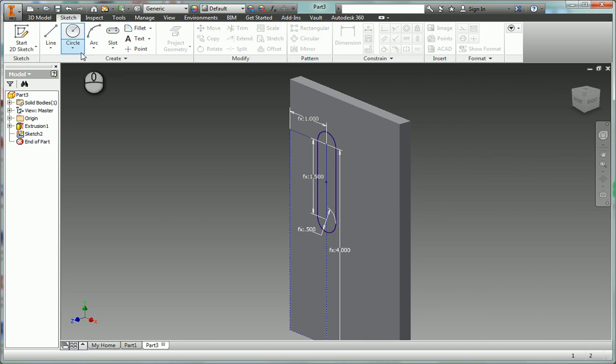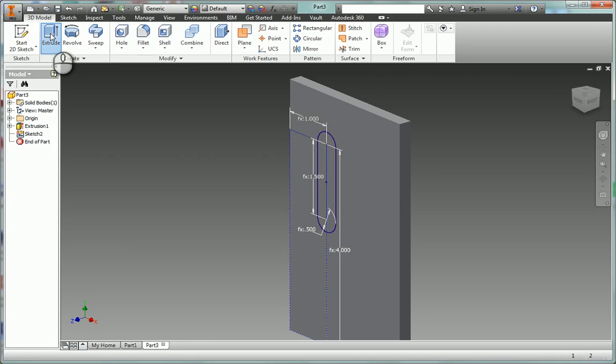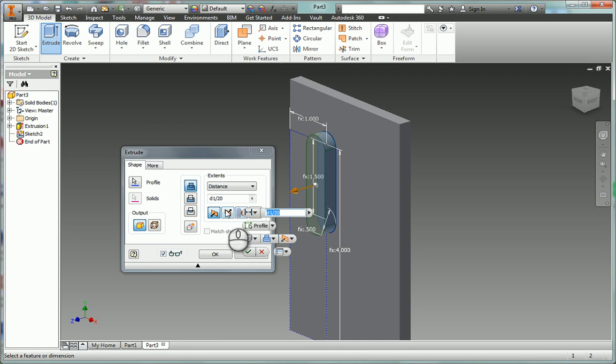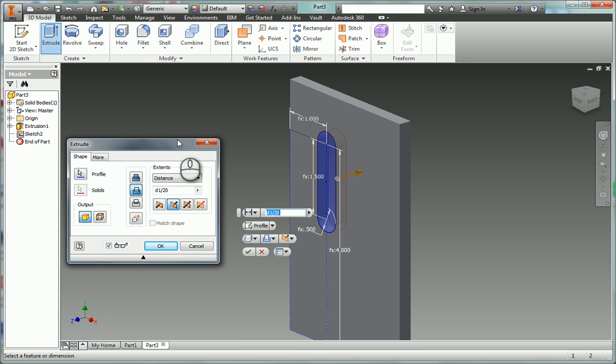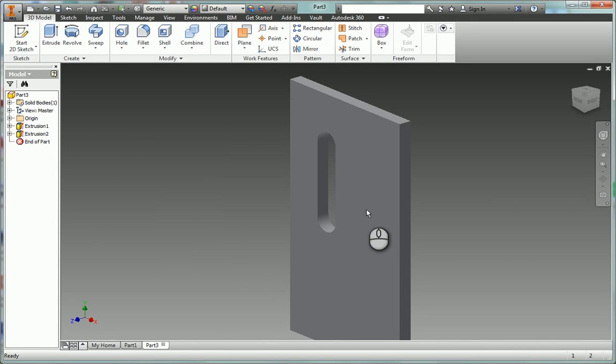And then I'm going to extrude that. Go to 3D modeling, go to extrude. I'm going to actually cut it out, though. And how far? Well, what does this be? This is slot extruded length, same as the plate thickness, which was D2. So I want to call this D8, so this will be D8 equals D2. I can just do it that way. And do that. Okay, good.